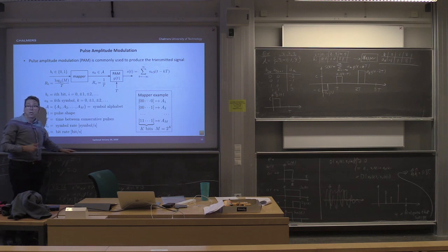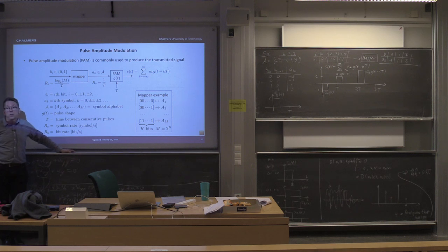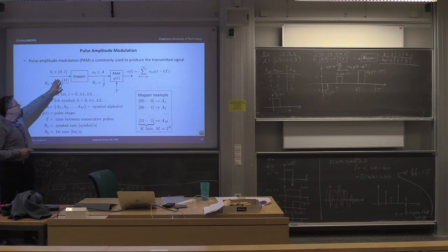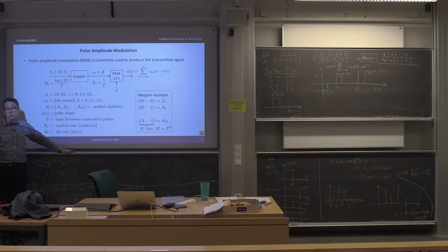So what is stopping us from doing this to have high data rate? That's a rhetorical question now, but you might know it already. There are 2 things that stop us. One is the noise level on the channel, because it turns out the more bits we transmit per symbol, the more sensitive we will be to noise on the channel, and we will get more errors.